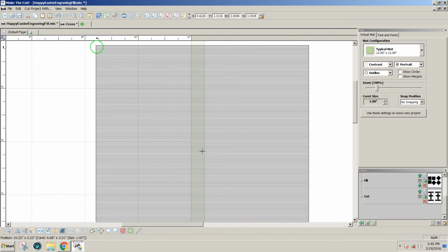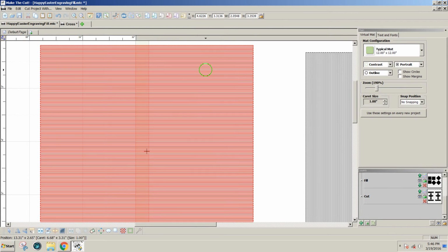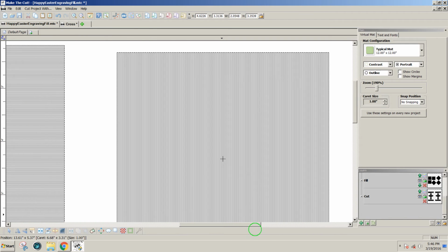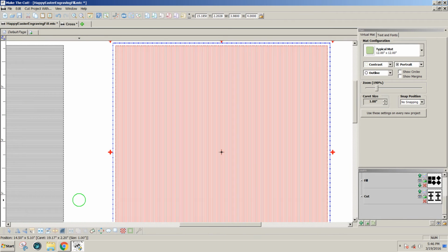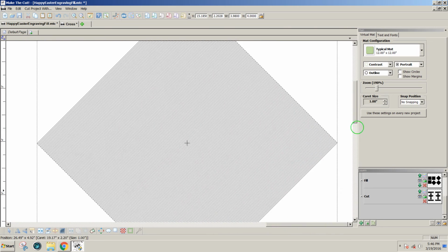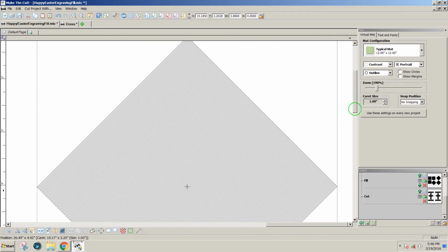It's a simple line multiplied, duplicated many times at 0.02 inches distance apart to create just back and forth lines with your pens or embossing or engraving tools. This one I've done the same thing, only rotated it to be vertical to create vertical lines. As some designs you may want to use horizontal and others you may want to use vertical lines. This one is the same idea, but the line fill is rotated diagonally to give you diagonal lines. And again, if you want diagonal lines in your design with pens, then you might use this filled pattern.